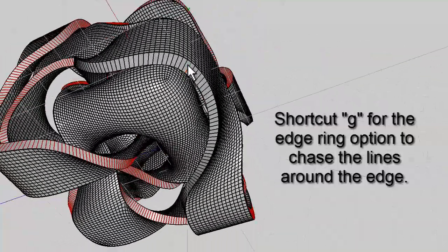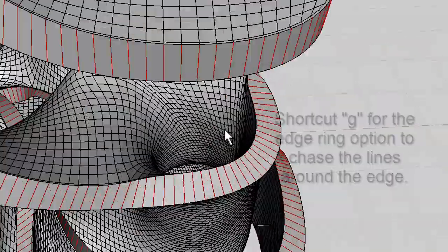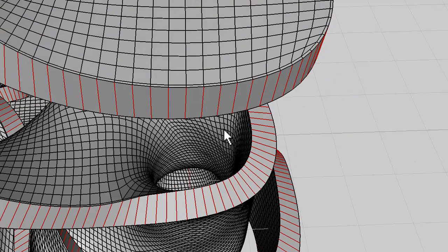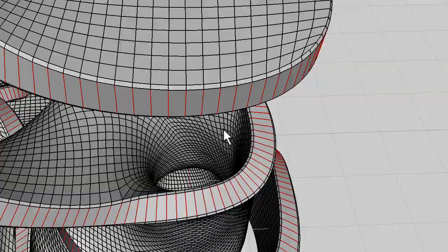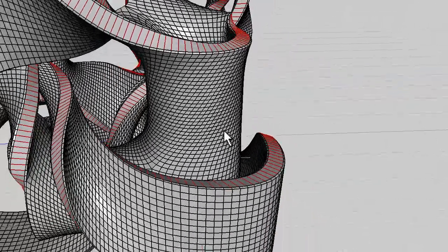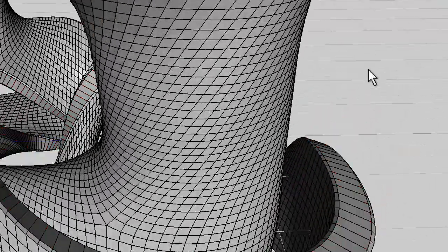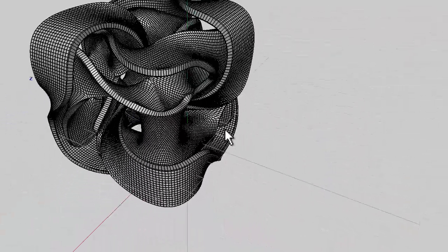I've missed one there, but you just turn the shape around and look, and then zoom in a bit and go scale uniform. And by doing it that way, you can create a chamfer on the edge of your shape like that. Aim for about 45 degrees, and that should help it to render nicely.